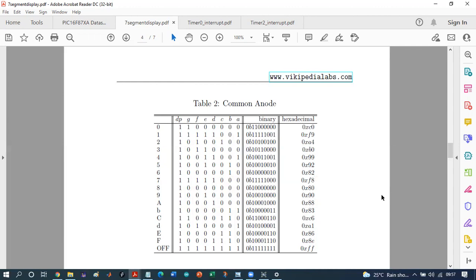So in hexadecimal form, when you want to convert, if you count this, 0, 1, 2, 3, 4, 5, 6, 7, it's 8 bits. So to convert to hexadecimal, we take the bits in fours. This one and this one. So 0, 0, 0, 0 is 0. Then 1, 1, 0, 0 is C. So this is the hexadecimal conversion table.